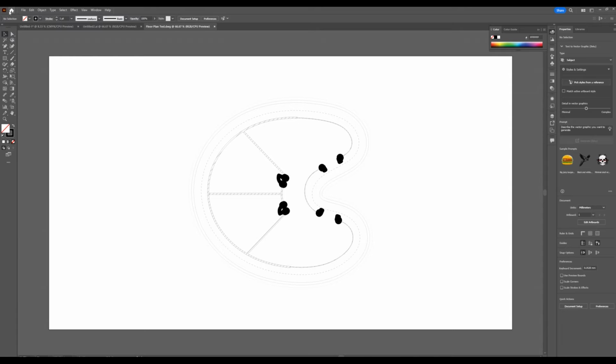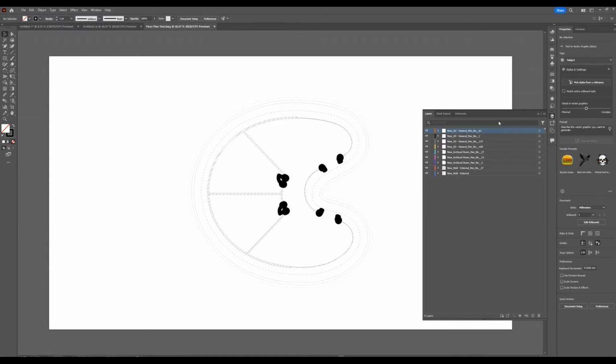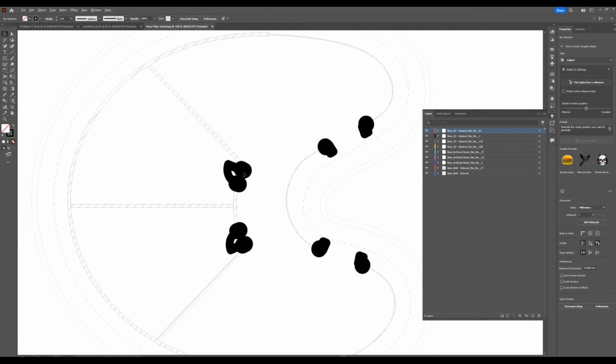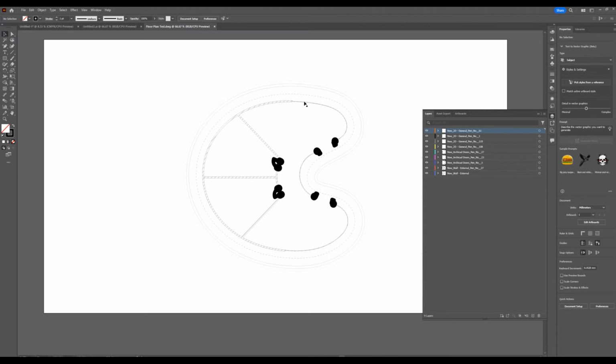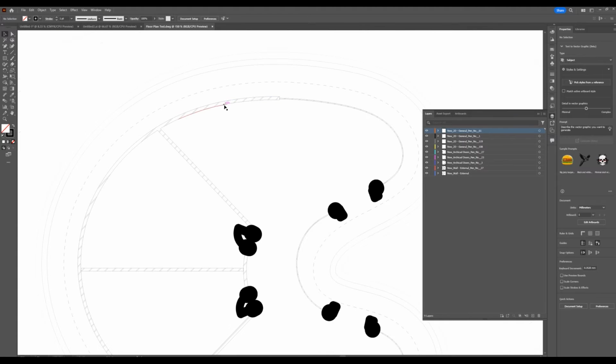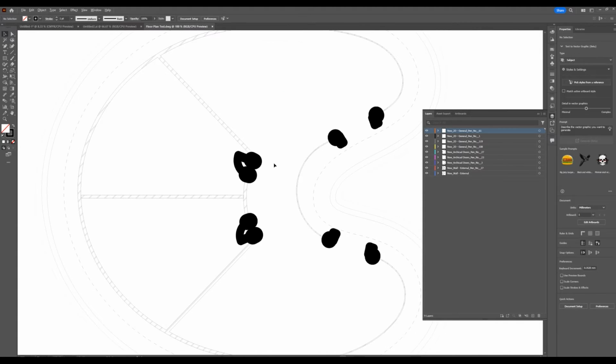And the good thing with exporting it as a DWG rather than a PDF, there's pros and cons, but in this instance, if we come over to layers, we've got everything in different layers. Okay, so all elements are on different layers. However, I can see that my doors came up a bit funny, and it could have been because of a line weight issue from what it looks like. And there's a few other issues here as well. As you can see, it doesn't have the black fill in here.